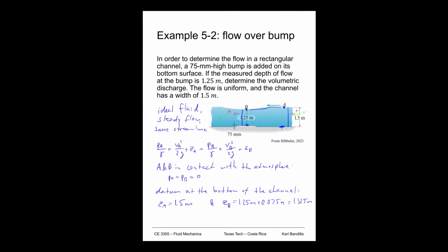So this approach is actually quite common if we have some kind of a channel that has water flowing through it and we want to know, over and over, what the flow rate is. Then we can just put a little sensor up here, a little eye that's looking downward that measures what the water level is here and what the water level is over here as well. And then just based on those two measurements, we can easily figure out what the flow rate in this channel is. So we could have a little computer program that just continuously tells us what the flow rate is. And if we needed to, maybe we have some control up here where we can make the water flow more or less if we need to.